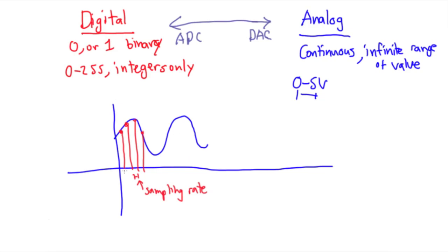And the idea is, the better the sampling rate, the more accurately you can capture all of these little signals. Another thing you need to keep in mind is that if this is a constantly moving signal of a certain frequency, your sampling rate has to be greater than this frequency by at least 2 times in order to pick up this signal. Say, for example, my sampling rate is half of this frequency. I'm only going to pick this one up right here, and then this one right here, and I'm going to lose this entire little chunk of data. So, things to keep in mind.